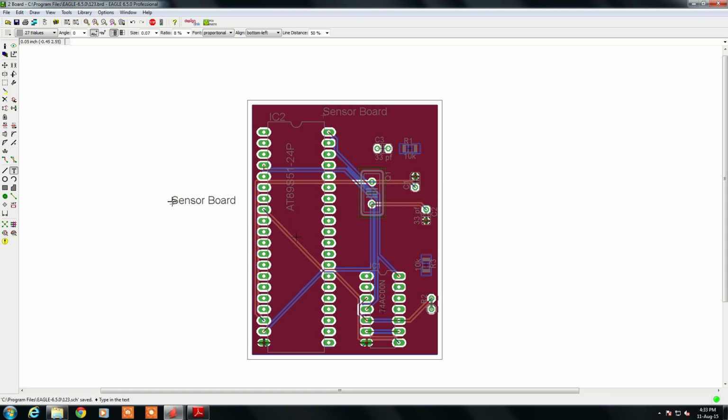And if you want to give this PCB to the manufacturer, then this is not sufficient. You need to create the Gerber files. So those are the files which a manufacturer requires, because the computer generated files, schematic and board, are not enough. It has to generate the Gerber files which a CNC machine can understand. So how to generate the Gerber files in Eagle?